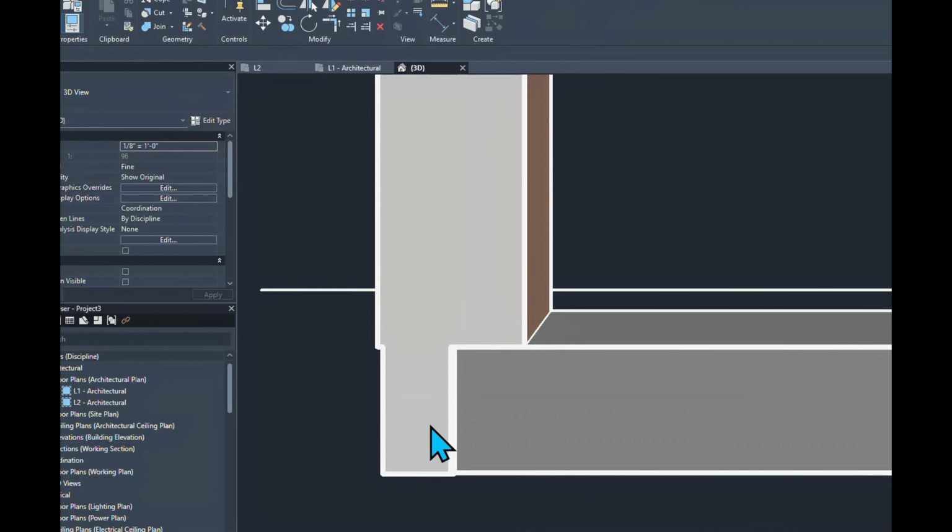You can adjust your modeling easily by simply selecting all the exterior walls, anything that is on a slab edge, and you can unlock that portion of the layer that you want to bring down and then extend it down and align it with your model. You can also do the same thing with the ceiling on the other side, right? So if you have a ceiling, half of the wall is the bottom of the ceiling, and you want to extend the other layer out because if it's going to be the exterior panel or anything that goes straight up, you can do the same thing on the ceiling side as well.